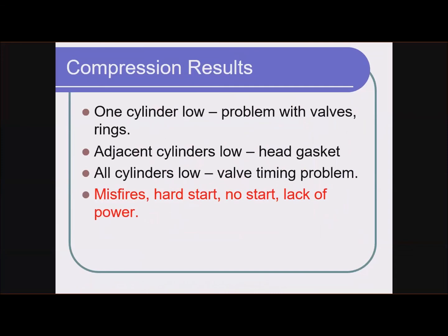Remember, you're doing this test because you're trying to diagnose something. So you're already looking for either a misfire, a hard start, no start, or lack of power. If I have a misfire and I find the lowest cylinder is only 70% of the highest, and that's the cylinder that's giving me a misfire, I'm going to call it a compression problem, definitely.